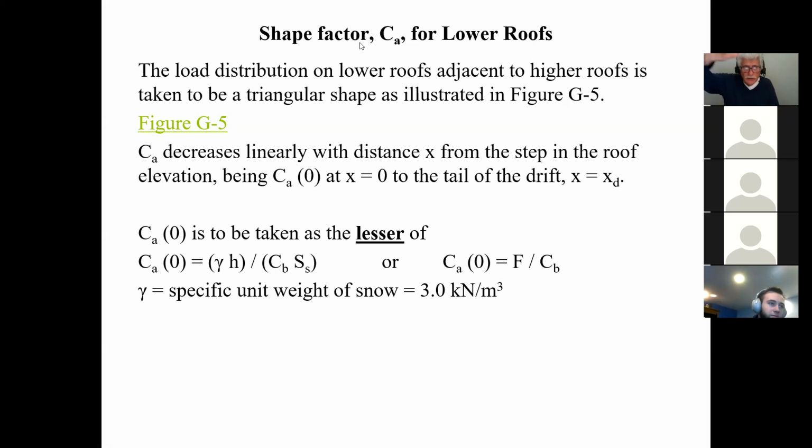When you see that nice fluffy snow falling to the ground, believe it or not, that weighs about 0.5 kilonewtons per cubic meter. Then once the snow gets onto the ground, it starts to crystallize and get more dense. So this is not the actual weight of fresh snow.